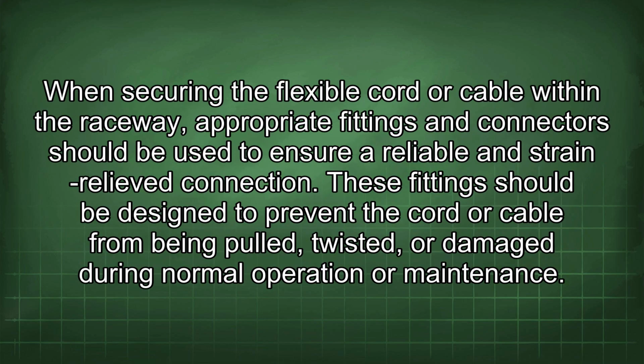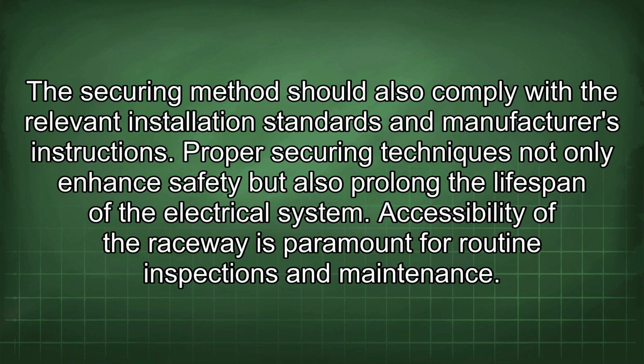When securing the flexible cord or cable within the raceway, appropriate fittings and connectors should be used to ensure a reliable and strain-relieved connection. These fittings should be designed to prevent the cord or cable from being pulled, twisted, or damaged during normal operation or maintenance. The securing method should also comply with the relevant installation standards and manufacturer's instructions. Proper securing techniques not only enhance safety, but also prolong the lifespan of the electrical system.